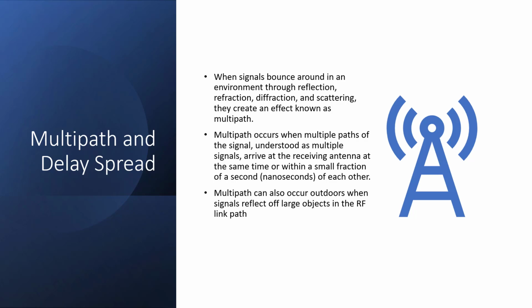There are several algorithms available to deal with multipath and delay spread. What is important as far as site impairment analysis is concerned is that if you have too much multipath effect, you will have more errors. How to avoid multipath? Sometimes it's not possible to avoid it. If you have glass doors, are you going to pull out the glass doors and put something else in?